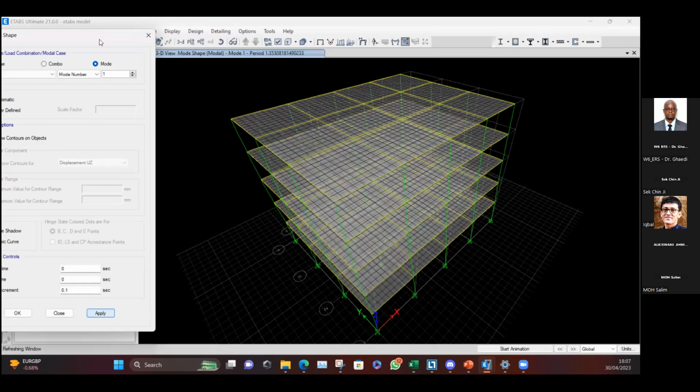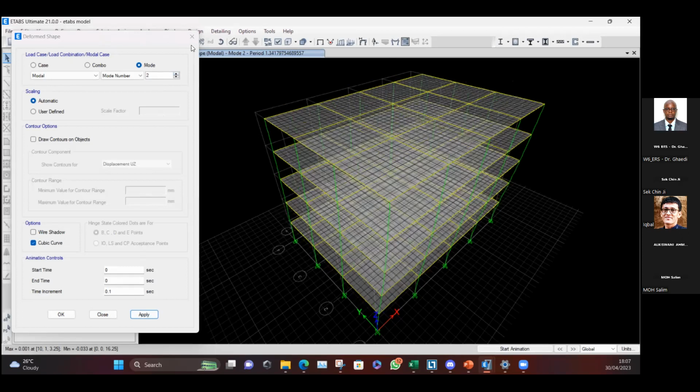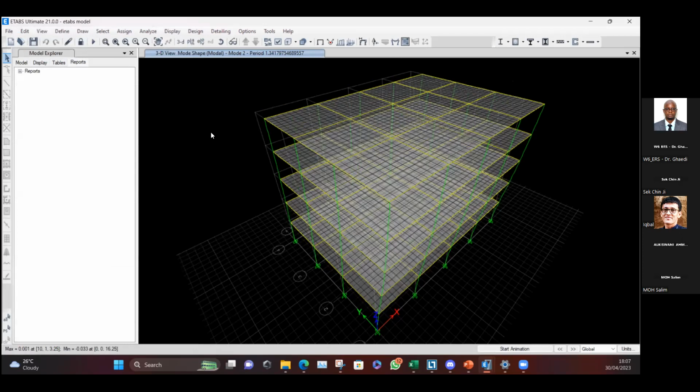It will increase. As we can see, the mode also in the X direction, here it's 1.35 seconds. So here we have a higher mode period, because the rigidity of the structure is less. So we'll have higher deflection and then a higher period. And we can see that also for the Y, it's 1.34. So in this case, we should see that the one that we calculated manually should be less than the one computed by the model. And we inserted approximately the same values, but let's see if he did it right.